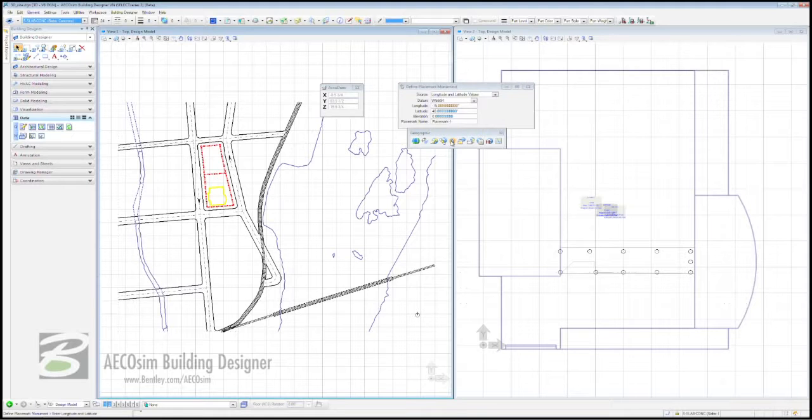We're going to click on this icon, 5th in from the left, 6th from the right, and you can see straight away that we have a source up at the top here. We want to click that and say Reference with Geographic Coordinate System. This changes the dialog box, and now we need to click on the jump box into Reference and select our C underbar Site 2D. We can also give it a fancy name, but Placemark 1 will suit our needs exactly,